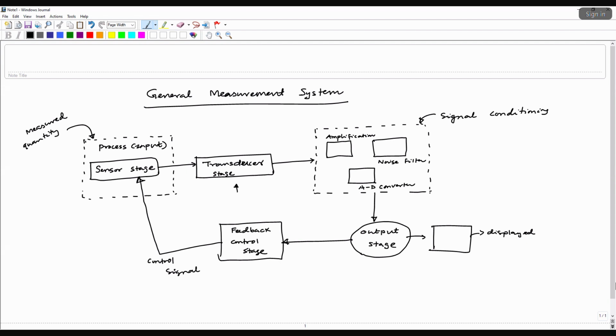And then at some point you would see that the way these thermal ovens work, it would slightly exceed the set temperature. Let's say you have set 80 degrees centigrade, it would go and exceed 80 degrees, it will go to 85 degrees, and then when it goes to 85 degrees centigrade, your feedback control stage should tell the heater to set a control signal that switches off the heater. So then the temperature goes down, let's say to 75, then it comes back to 82, then goes down to 78 and oscillates, and finally it reaches 80 degrees, right?